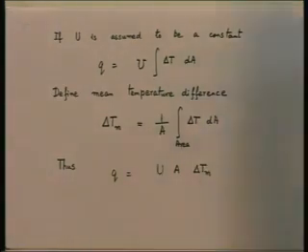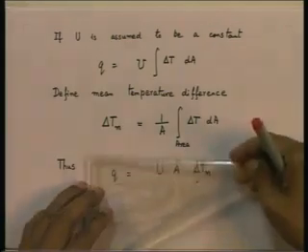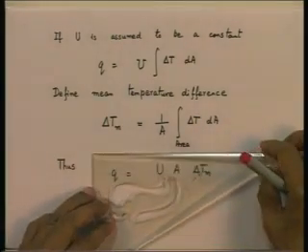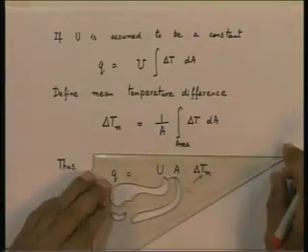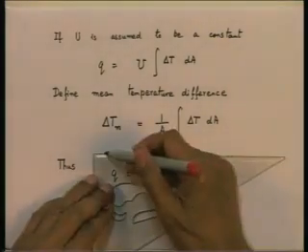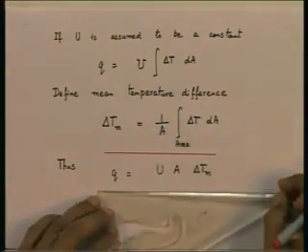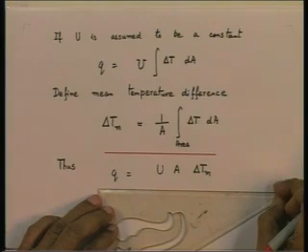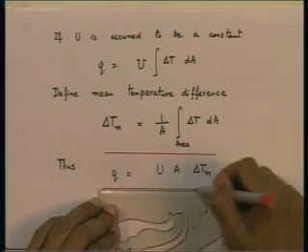And what we have here is the basic performance equation of a direct transfer type heat exchanger. Let me put a rectangle around it to say this is an important equation which we are going to use for calculating the performance of a direct transfer type heat exchanger.